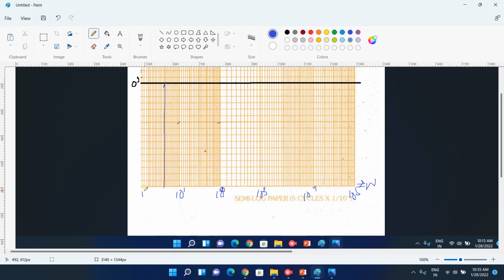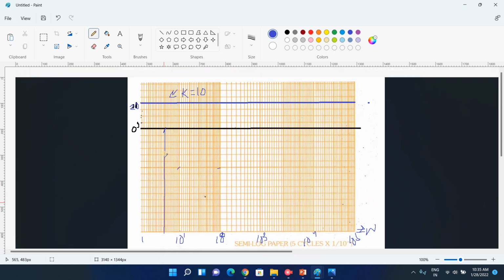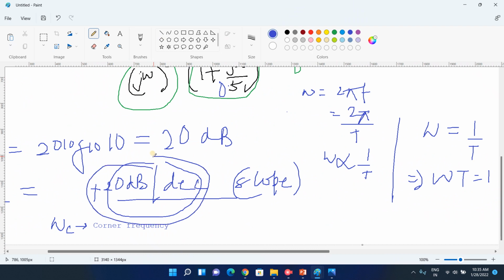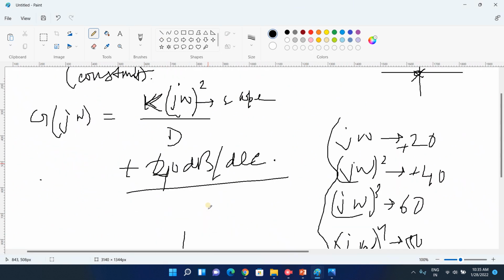Okay, so x-axis starts from here. Okay, it is starting from here 1 to 10, so this will be 5. So this line is 5. Okay, so you don't have to represent this one. Okay, this is 5. So our line will be like this. We will draw again from 0 to 5 a straight line. Then from 5 we will plot the plus 20 dB per decade slope.